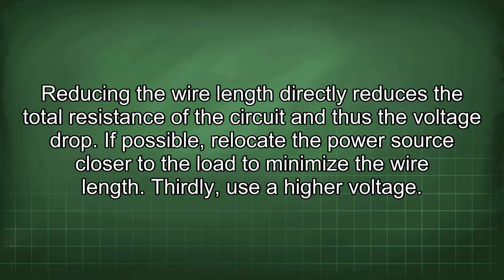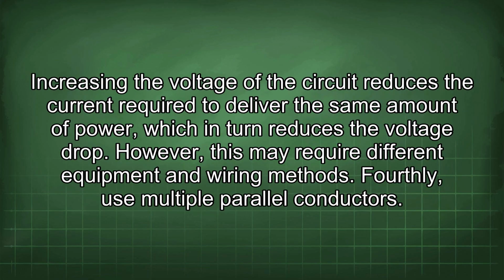Thirdly, use a higher voltage. Increasing the voltage of the circuit reduces the current required to deliver the same amount of power, which in turn reduces the voltage drop. However, this may require different equipment and wiring methods.